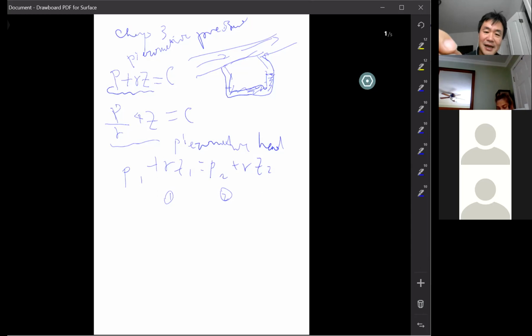Okay, so that's the key, hydrostatic. That's why we can apply this hydrostatic principle to solve the manometer problem like this. If you are in the flow, you have points A and B. How do you measure the pressure difference between A and B? You can't directly compare A and B using the hydrostatic principle, because A and B are in the flowing fluid. In the flowing fluid, the hydrostatic principle doesn't apply. Between A and B is hydrodynamics. They're moving, right?